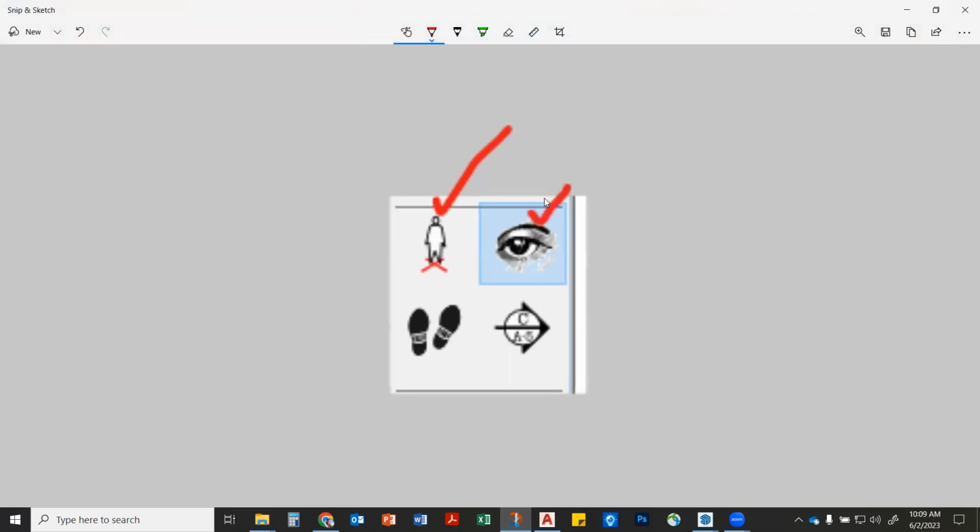This little eyeball one, you can move around, right? You can look around different views. This one, you can actually walk through the model, right? You can do like a little walk, which is kind of cool. And then this is the section. I'm going to show you how to make a section, okay? It's super helpful because if you've already made the model, you can make as many sections as you want out of there. Then you can export them to Layout and scale them to what you want them to be. Cool?